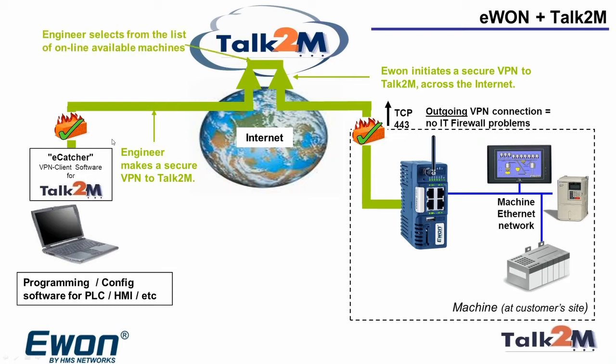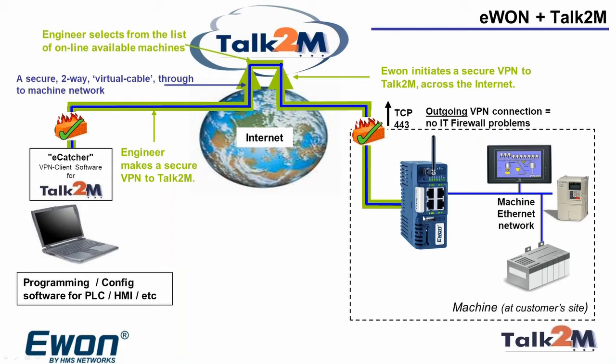So at that point, you can now see there is a routed path between this laptop on the left-hand side through the Talk2M through to this Ewon. And at that point, you can then make a connection through to the Ewon and through to the devices behind it. In effect, what you're doing is you're making a very long cable all the way from your laptop on the left-hand side through the Talk2M cloud, all the way through. So your laptop is effectively joining the cables on the right-hand side inside this machine network.